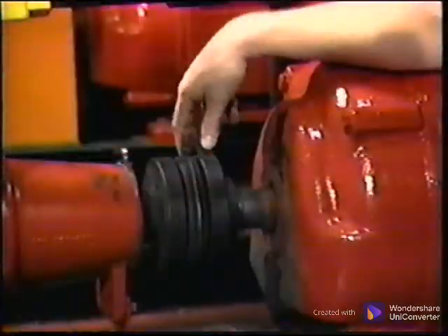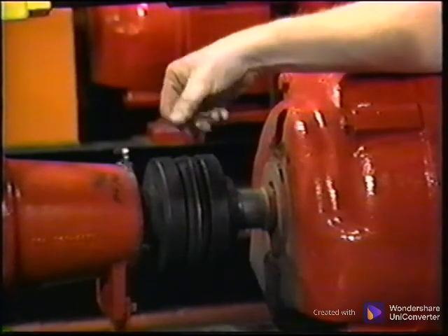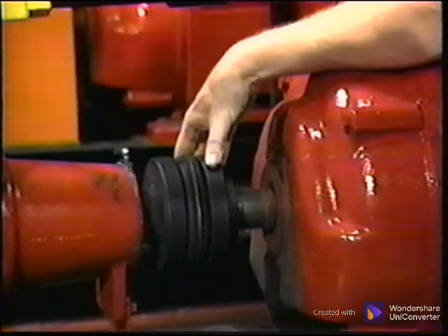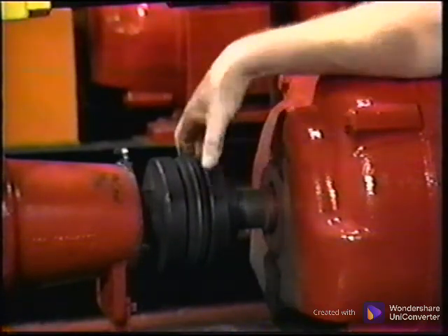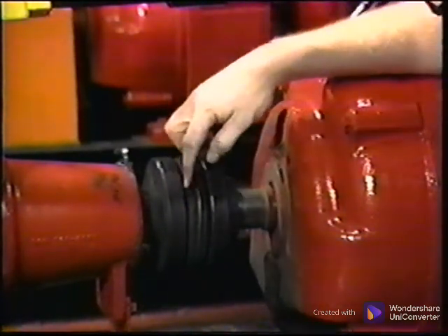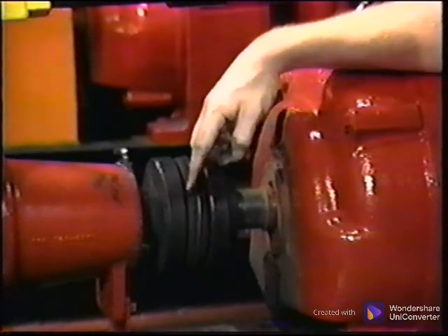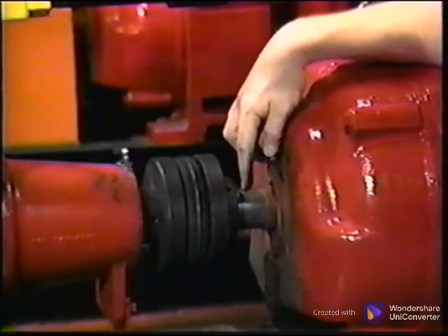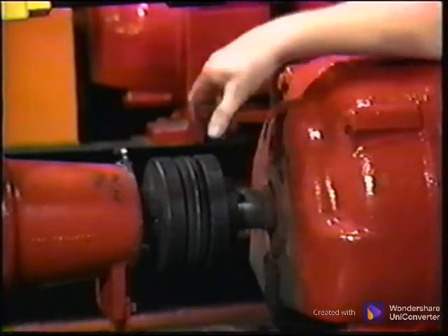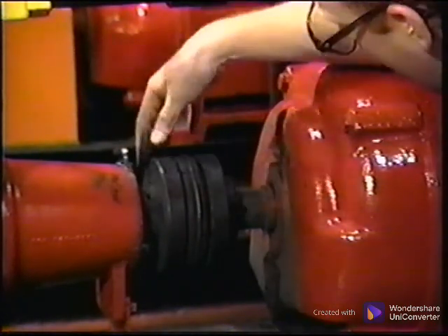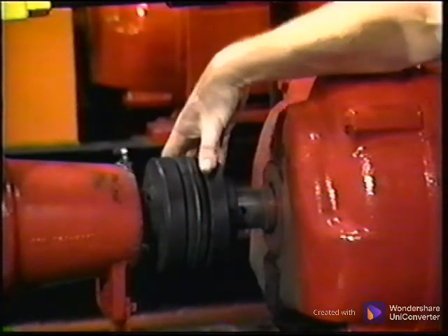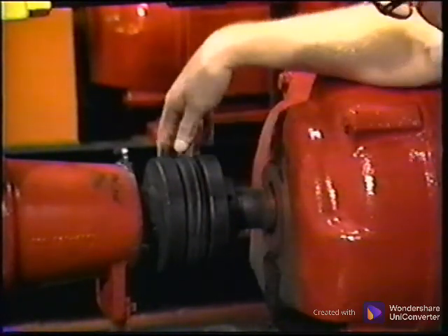If the coupling has a rubber insert, check for rubber powder, because this is an indicator of the amount of misalignment, and a worn rubber insert can allow too much looseness in the coupling, accelerating the wear and increasing the vibration. On lubricated couplings, check for leaking grease as an indicator of wear or looseness. Check the keyway for wear and a loose key as an indicator of a loose coupling. Check the coupling for tightness and any play between coupling halves, including movement in the axial direction.